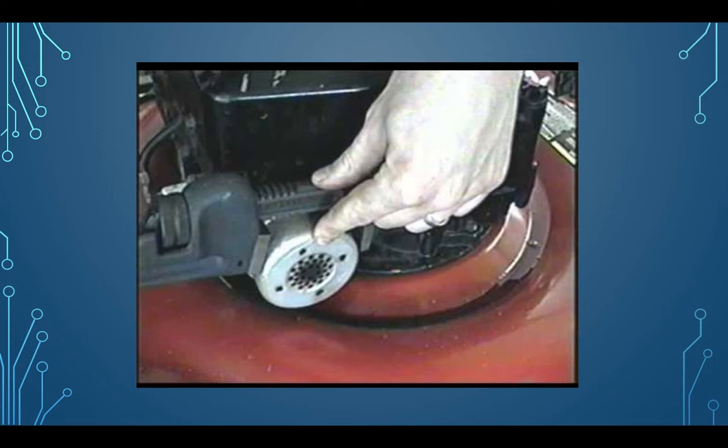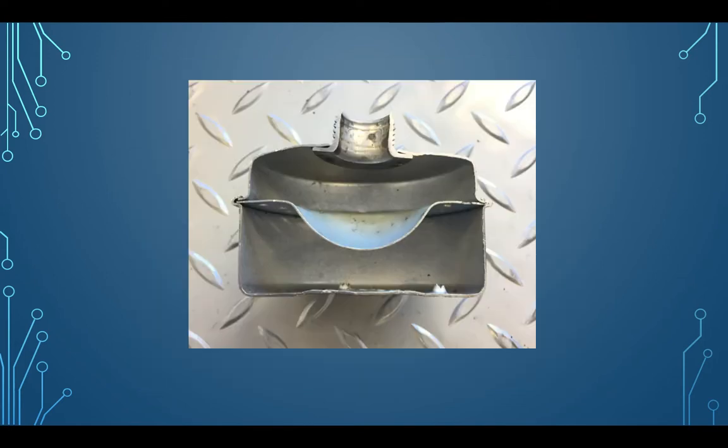The muffler is believed to be produced through sheet forming methods due to its seamless nature of the thin walls and appearance of the holes. This suggests that it was created by forming together three thin metal sheets. These sheets were plastically deformed by tensile stresses in the process of deep drawing.